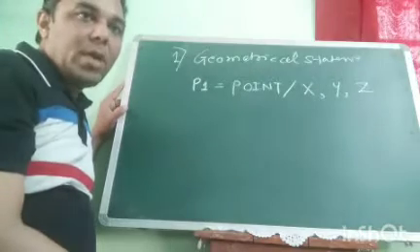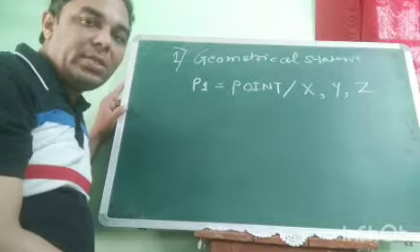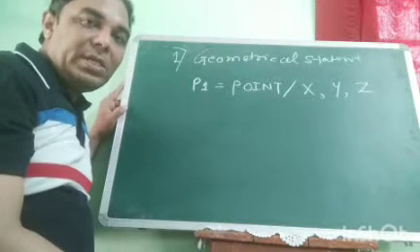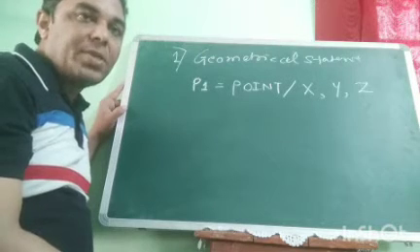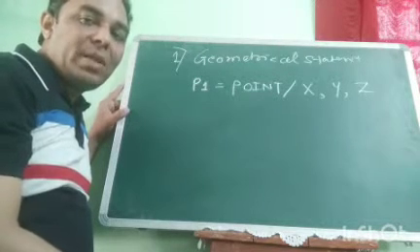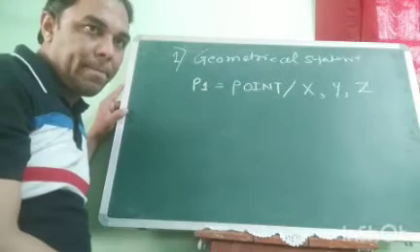Why do we need to write the x coordinate, y coordinate, z coordinate? We have seen in the previous lecture that APT part programming is a 3D space language. Getting me or not? So we need to mention the x coordinate, y coordinate, and z coordinate simultaneously.